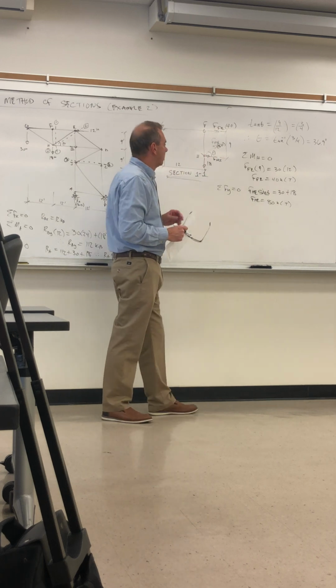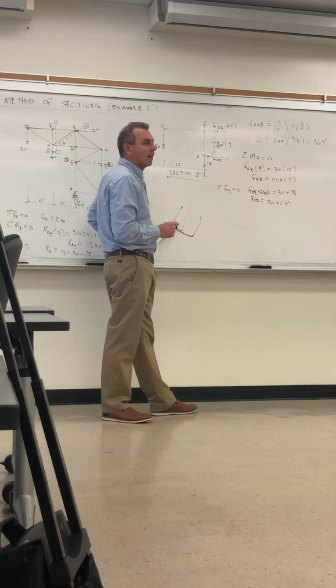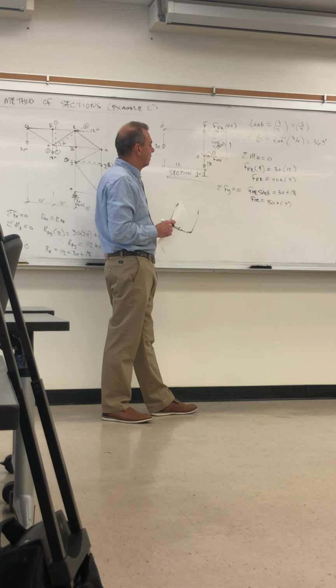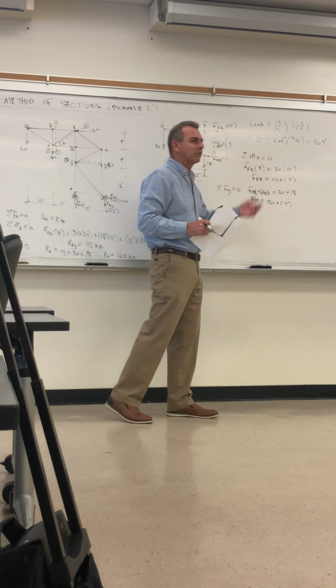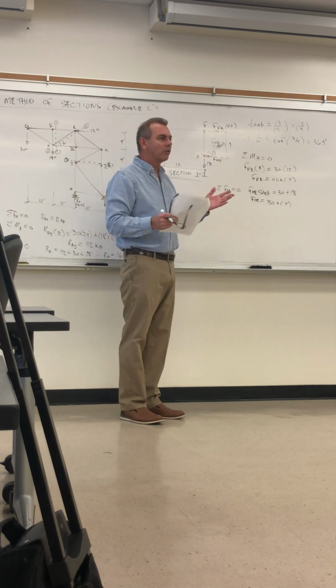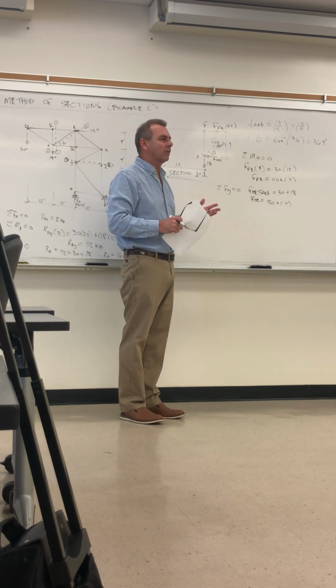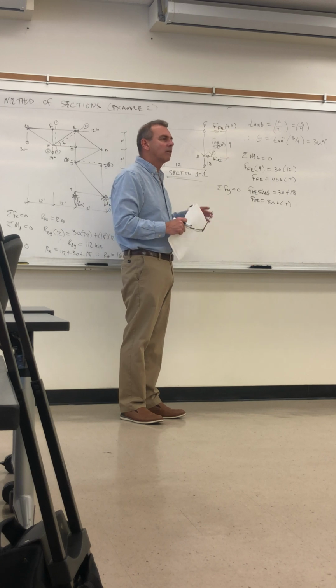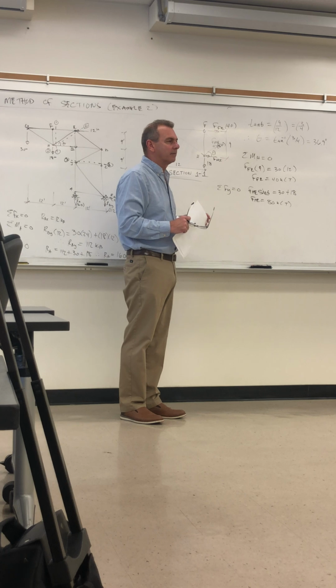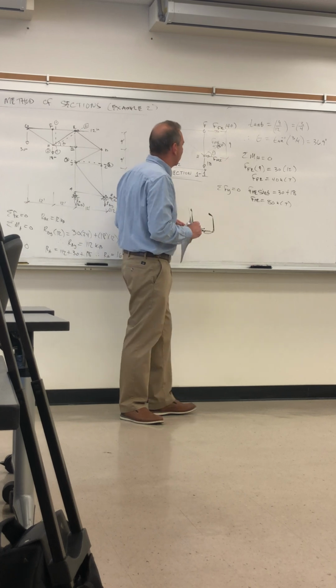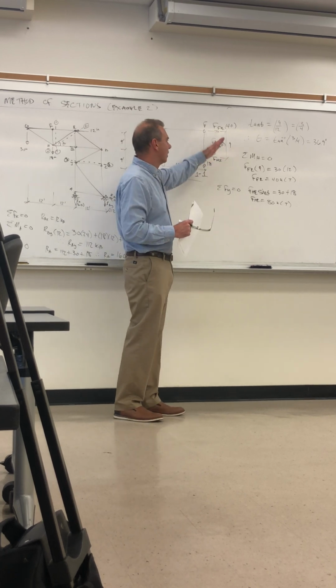So would it be safe not to draw an arrow until we figure out if it's going to be tension or compression? No, you have to draw an arrow because then you can't sum forces or moments or anything. If you don't draw an arrow, you have no idea how to sum forces. You have to draw it one way or the other, and then see what you get. If you don't draw an arrow, you have nothing, except a line.